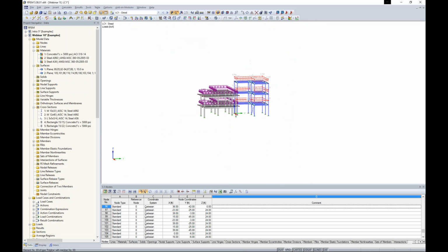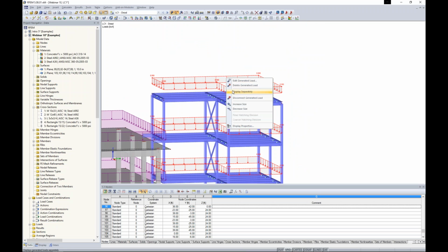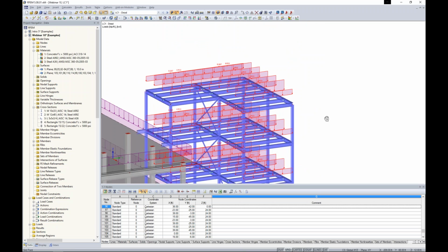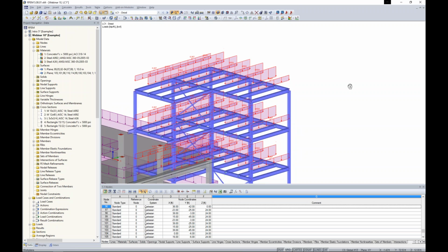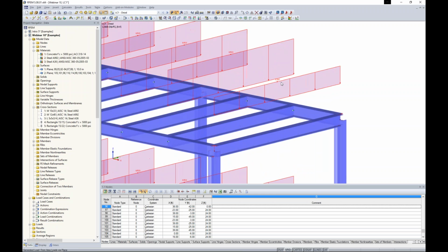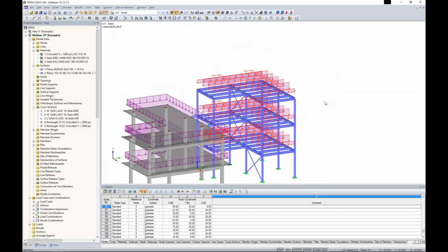The program will automatically create this area load, which we can see by this faint gray line here. And maybe I'm interested to see how this load was applied to each member. Well, I can right-click, display separately, to see that I'm only applying it to these members in the global Y direction, and I can view the magnitude by zooming in here as well. So just a quick application so the program can automatically figure out these tributary areas.